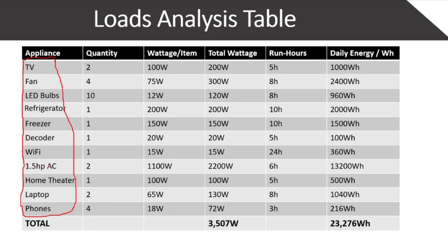So even after your load analysis, during your installation, if you have not added an appliance here, do not connect it to your solar. Make sure that you always remember that.